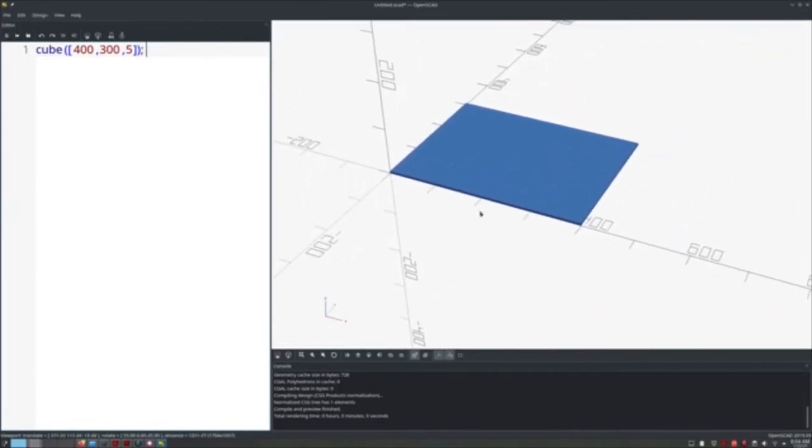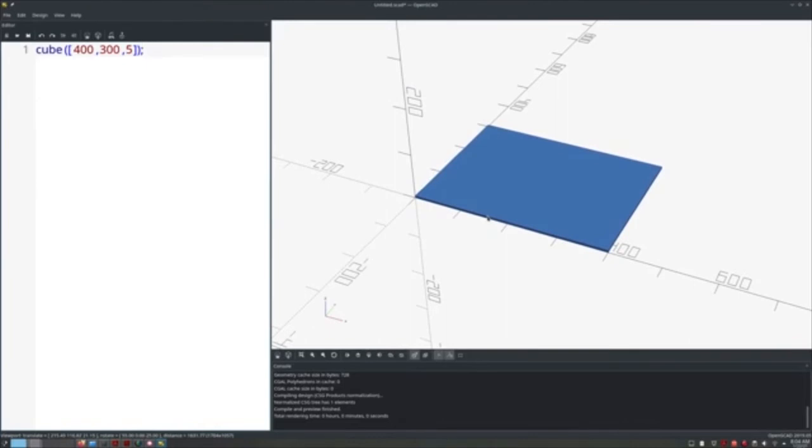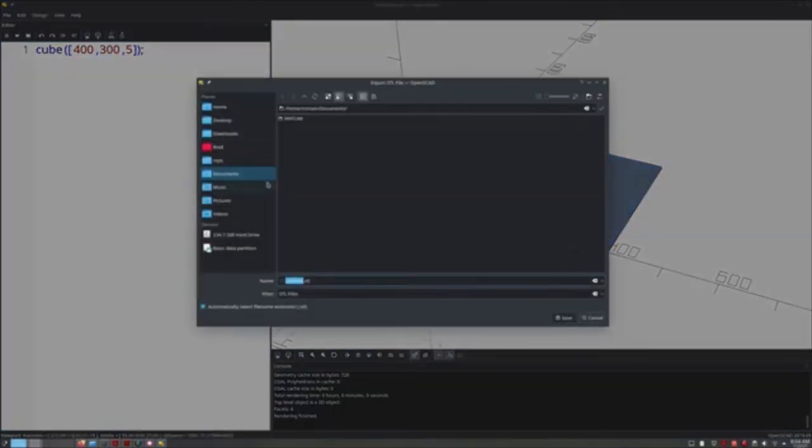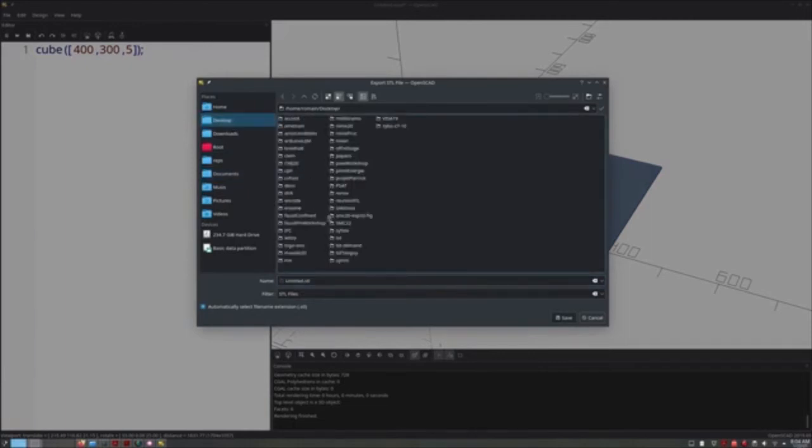Awesome. So, this is a very simple example, but it's just to show you how this works, so we're done with Openscad. We did what had to be done. Then in Openscad, we need to render, so basically mesh that object, which is something we're going to do by clicking this button here. Okay, so this is done. Can take a lot of time if the model is a complex model. And then we will export that to STL, and STL is a very standard format for that kind of things out there.